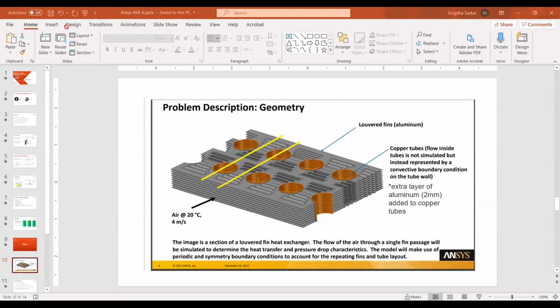Because if you knew the pressure drop for a particular velocity through that particular layer, you could just go ahead and do that. And if you wanted to include the layer for the sake of heat transfer, then there's a way in Fluent for including the heat transfer in a porous region. There is a thermal equilibrium method, and then there is a non-thermal equilibrium method. So we could do that.